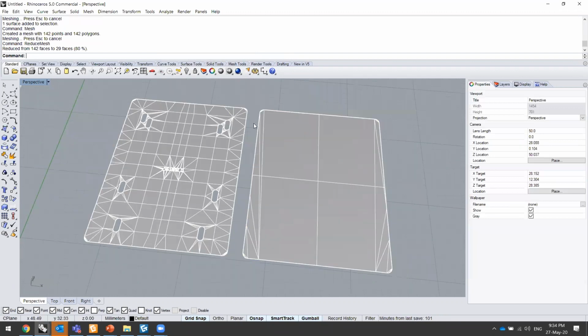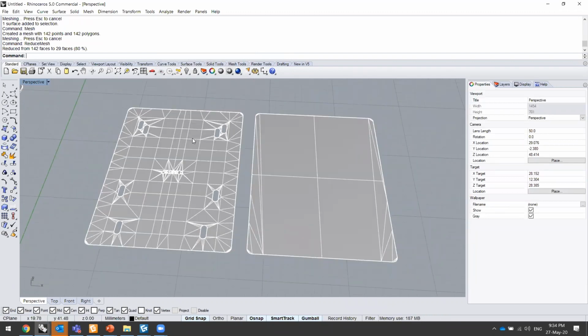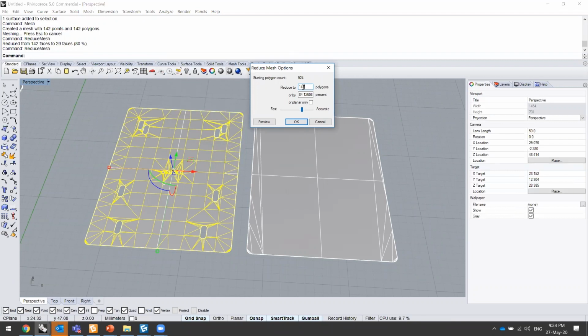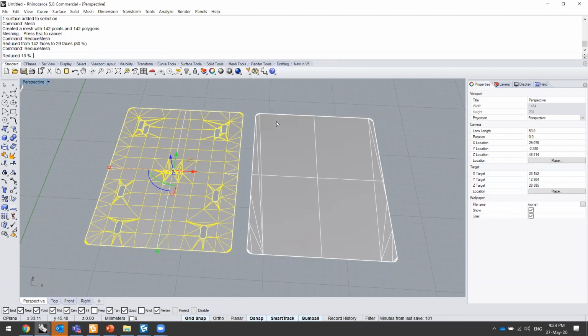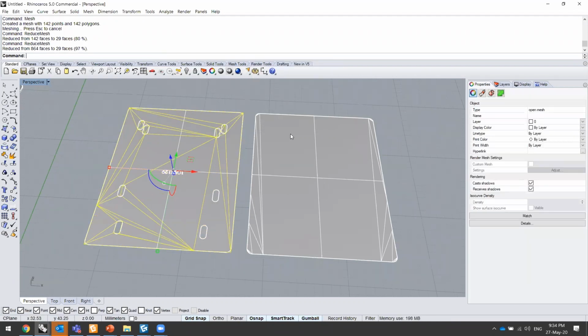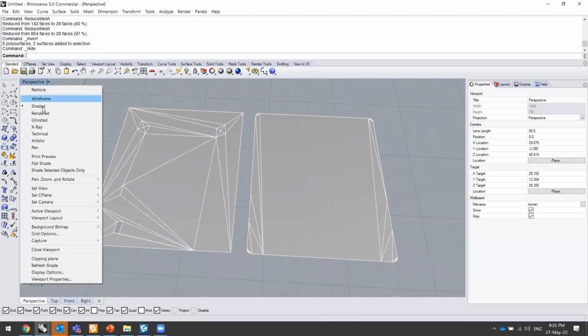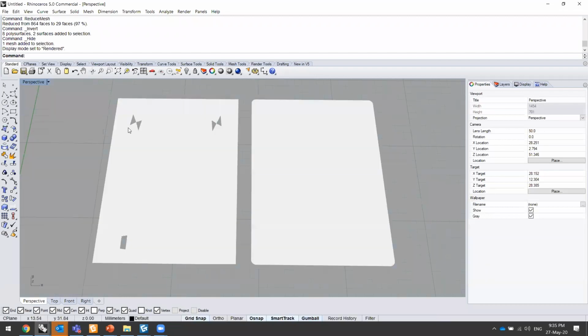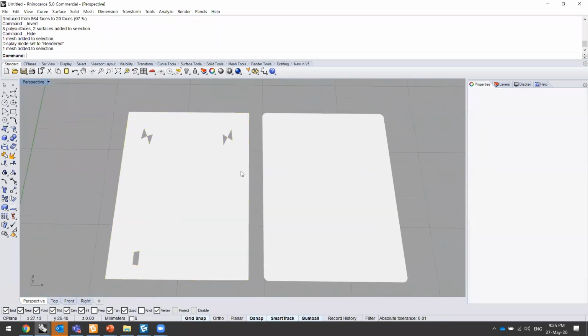You're going to get a decent polygon regardless. If I'm reducing this, it starts with a 900-number polygon count. I'm reducing this to the same polygon budget, in this case 30. So the reduction, these are the elements that are important, the fillet, and this doesn't really know where it wants to locate. The holes don't appear nice. It removes all the features from my intended surface. So yeah, this is the main difference.